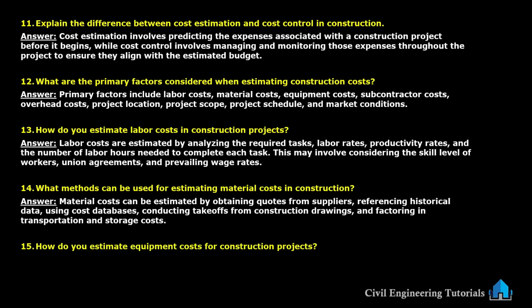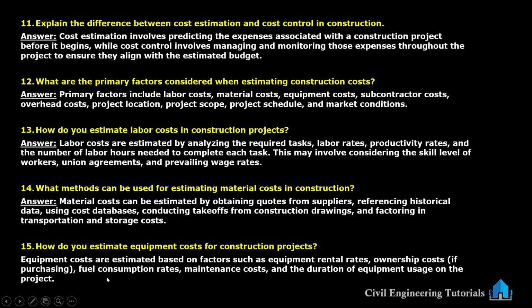How do you estimate equipment costs for construction projects? Equipment costs are estimated based on factors such as equipment rental rates, ownership costs if purchasing, fuel consumption rates, maintenance costs, and the duration of equipment usage on the project.